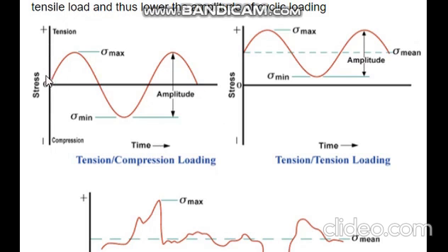You see, at time 0 there is no load or no stress. As time elapses, the load increases to a certain extent, reaches a peak, and then when time goes further it falls down to 0. And you see, on the positive side, if we take it as tension, and on the negative side as compression, initially the load goes to a peak on the tension side and becomes 0, and then further it comes to another peak on the compression side, and then it comes to 0.